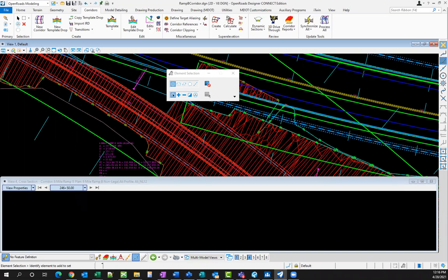Probably what I would do is, in your template, you could tell it to search for a specific elevation, but if you drew the berm in plan view, instead of using the target aliasing, how I just showed it, you might have to physically draw the berm and maybe use a point control or something like that to get it to fill in how you want.